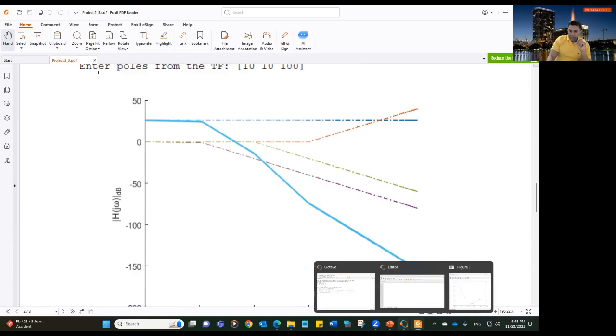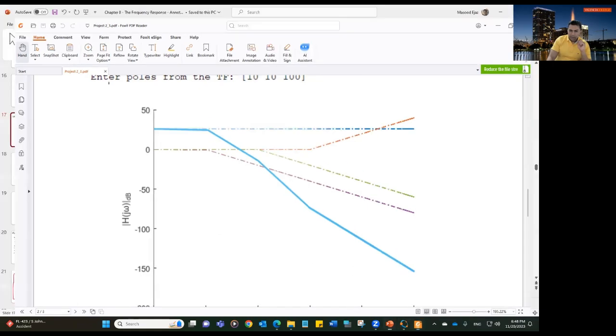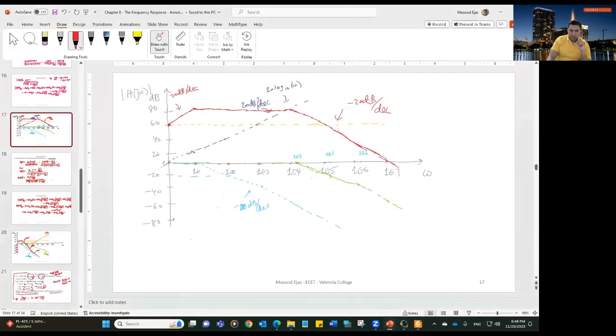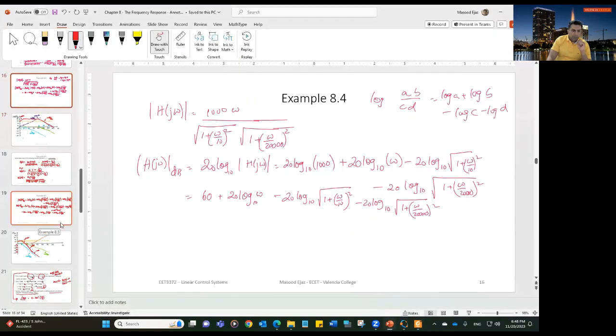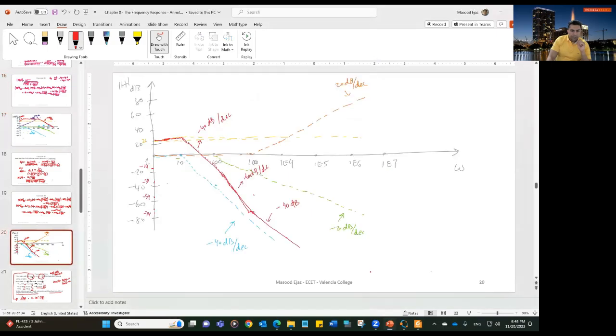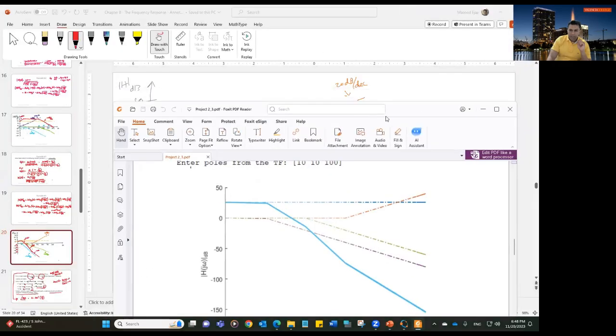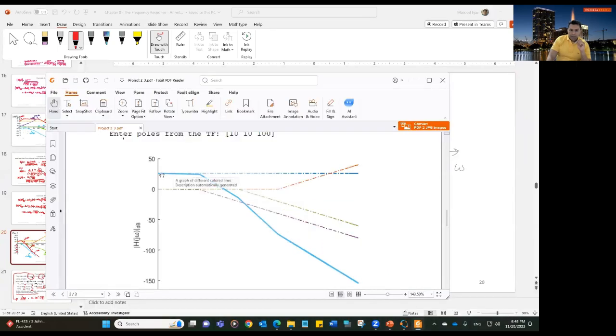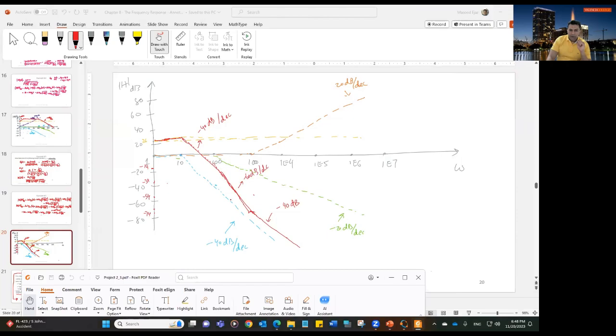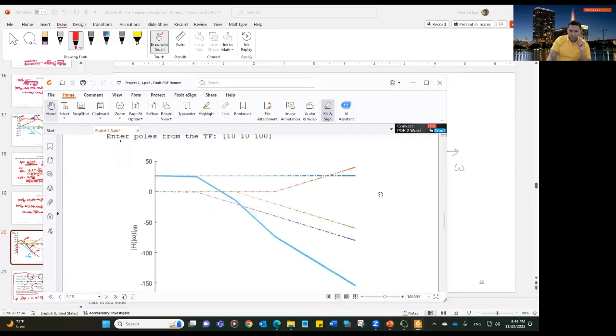So this curve is basically, which one was that? No, not this one. This one. So this curve is this, because it's the same function that I'm using. So you will see the curve is the same. Whatever gain is there, then it's going to drop by -20 decibel per decade, then -40 decibel per decade, and then again -20 decibel per decade, which is -40 decibel, -60 decibel, and -40 decibel. So that's how it is decreasing.